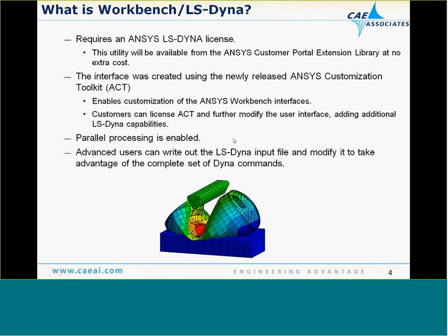Parallel processing is fully enabled, so if you have the license for it, you can use parallel capabilities. If you're an advanced Dyna user, you can write out the .k file directly and then add additional commands to the keyword input file, which is the Dyna formatted input file.